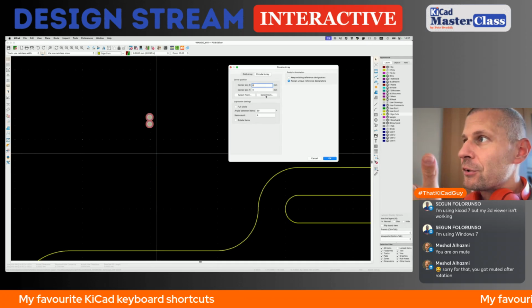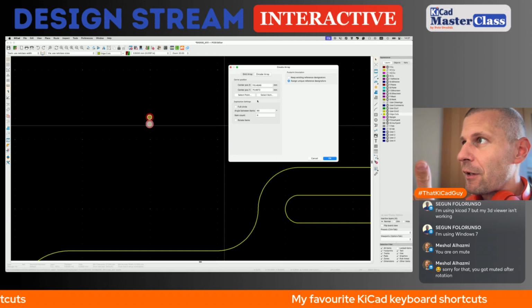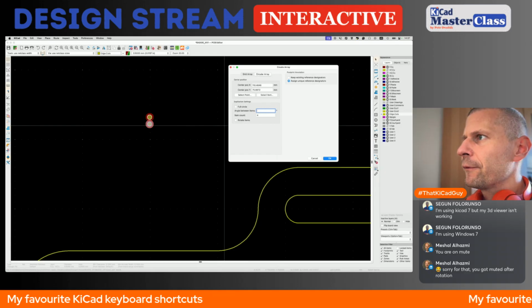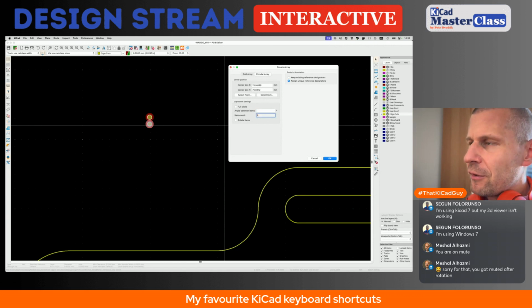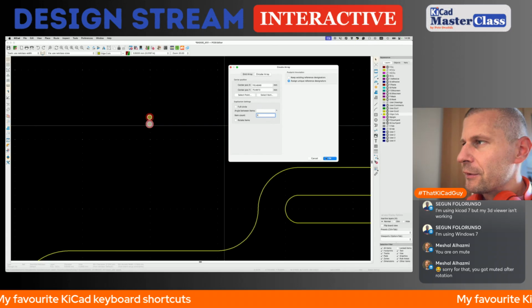So change select item. This will be our source item. Yeah, these are the absolute coordinates. And I want to place like 9 items. Angle between items will be... I think when I enter the item count, the angle will be automatically calculated. So let's try it.